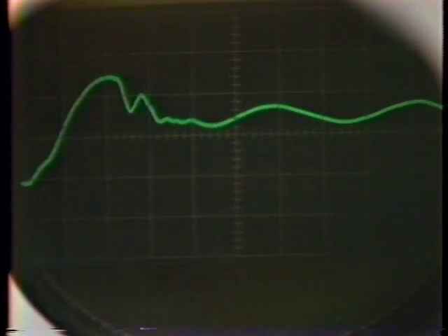Again, we have the perturbations from the mechanical imperfections, particularly as the speed changes. The motor overshoots, it now tries to slow down, and momentarily the gears disengage. You get the teeth in that area. And you see then the gentle rocking later on that's reflective of the basic low phase margin of the system. We'll do another one.